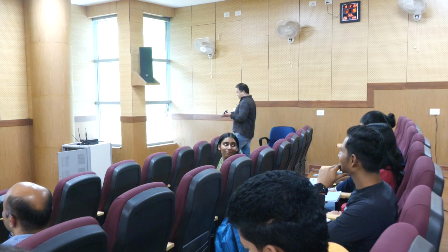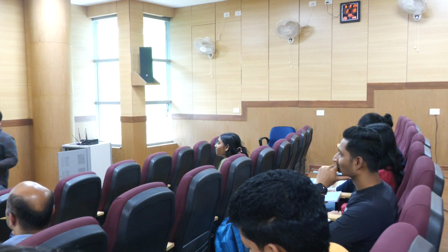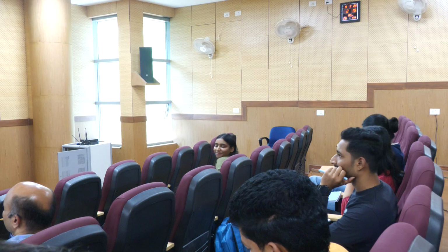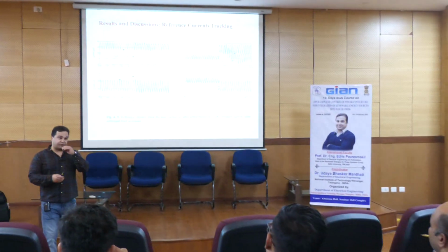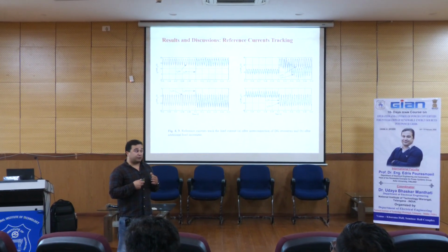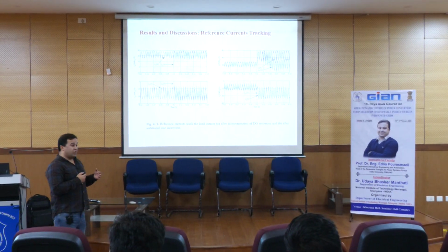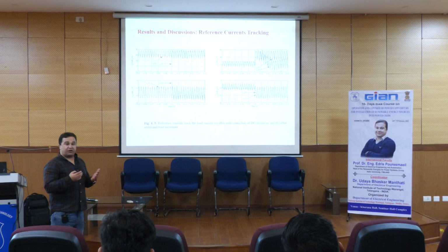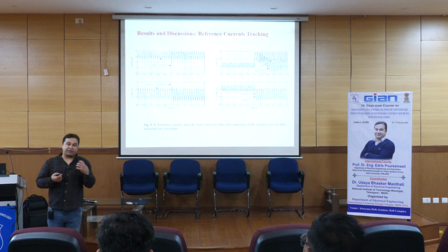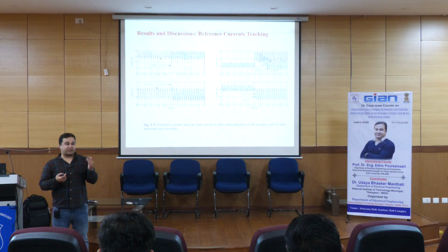So by this assumption, we can conclude that you can control your converter in a way to compensate any part of the load which is in the priority. For example, if I have a load that needs reactive power, then my priority is not to compensate the active power. My priority is to compensate the reactive power, and if I find more power available, then I can go through the active power. Because buying the active power from the DSO is much cheaper in comparison with the reactive power.